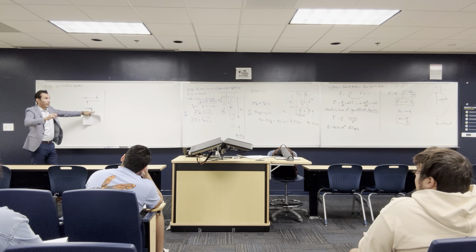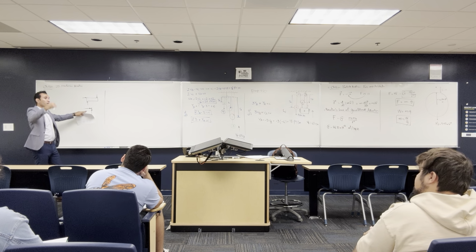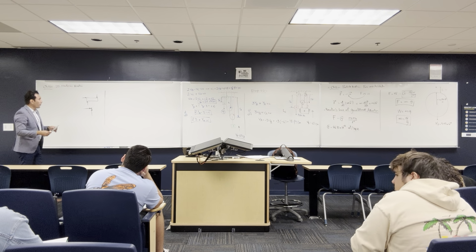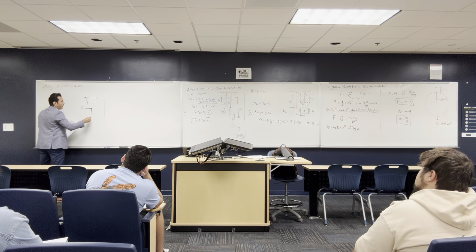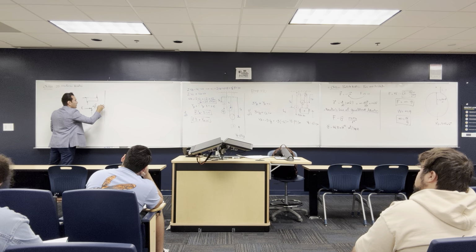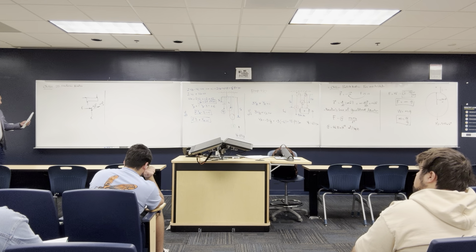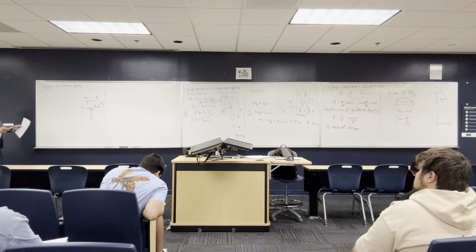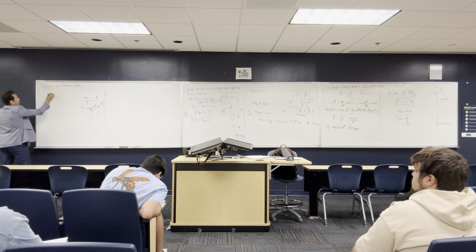But all what we are doing right now, chapters 12, 13, 14, 15, is all on particles. In chapter 16, we're going to take rigid bodies. Here we can apply the rule: if you have a bunch of forces like F1 and F2, you need to find the equivalent of these forces, and then the equivalent is going to generate acceleration, and the mass multiplied by the acceleration is going to be equal to the force F. So Newton's second law is the summation of the force F is equal